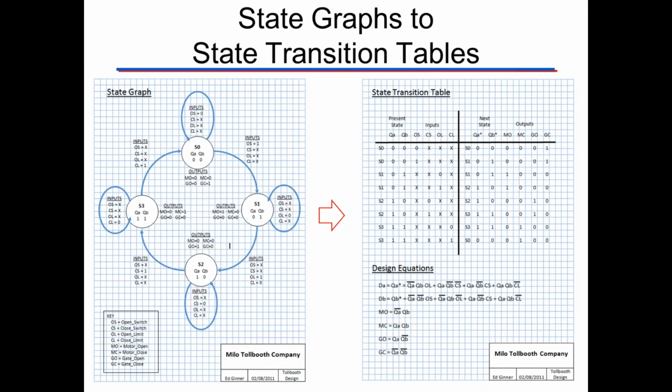So last video we went over the state graph, and one thing I want to give a little reminder about is the two parts to a state. Remember, we have part one where it's in, I'll call it the idle state, where it stays in the state, there's no change. Then something on the input changes and we have this transition arc and we go to the next state. So that's part two of that. So in keeping with that theme, what I'd like to do is go over here to our state transition table.